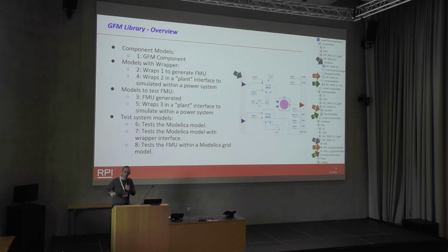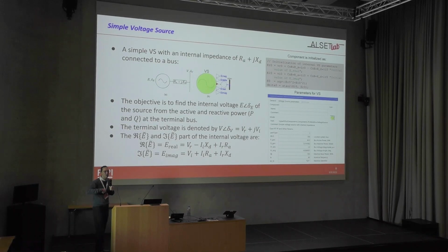So the idea was to do all of the testing that I could possibly do before putting it into another simulator within Dymola. Why? Because running the stuff in that simulator is extremely convoluted, and it takes not only time, but it's very error prone. So I wanted to debug everything in Dymola, and when it was ready, I could test it in the target, and then in the offline mode of the OPAL-RT simulator software, and then in the real-time mode, which I couldn't do myself because I didn't have access to facilities, all those guys did.